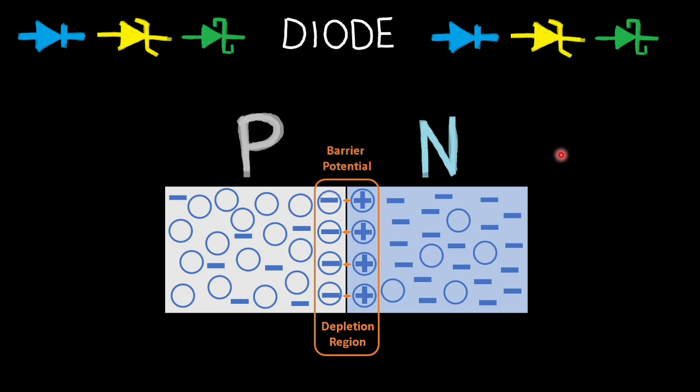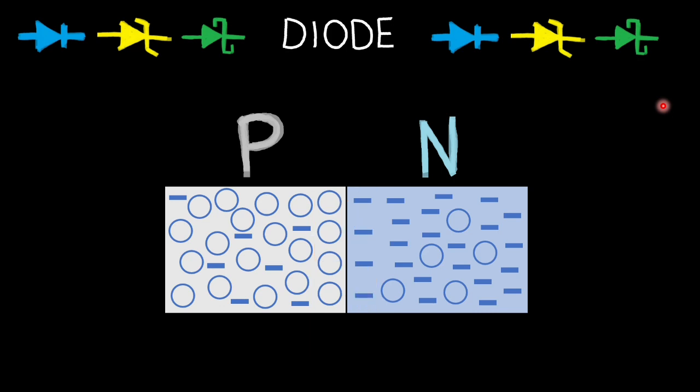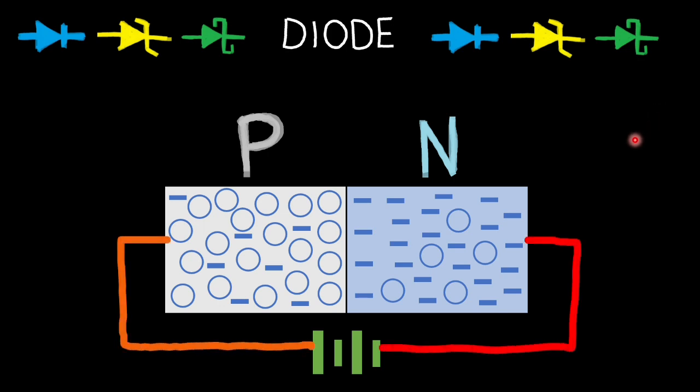In this case, we need some amount of voltage to break this region so that current can flow. In some textbooks, you will see the definition of this needed voltage to break the barrier potential as the forward voltage, knee voltage, and the threshold voltage. Okay guys, remember that two charges of the same polarity repel each other and two opposite polarity charges attract.